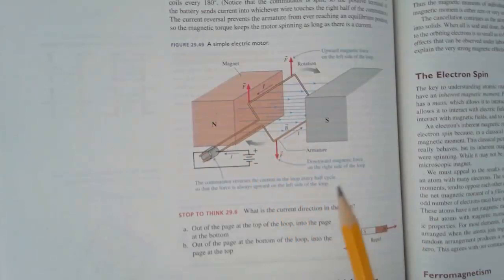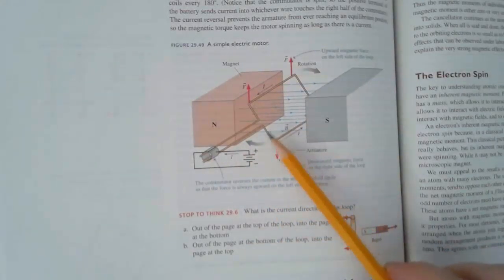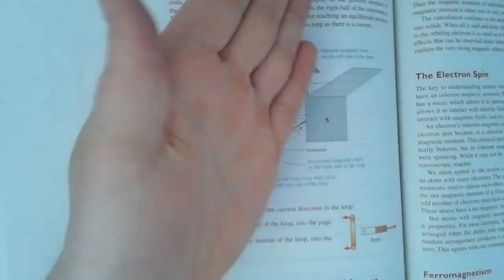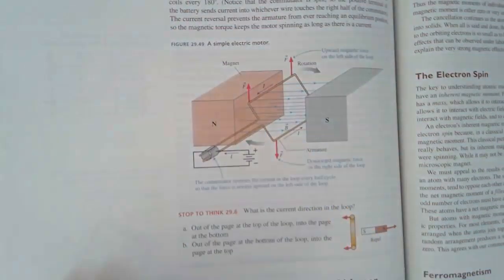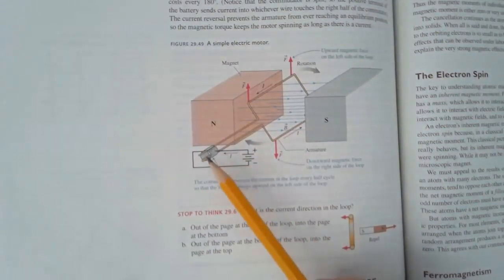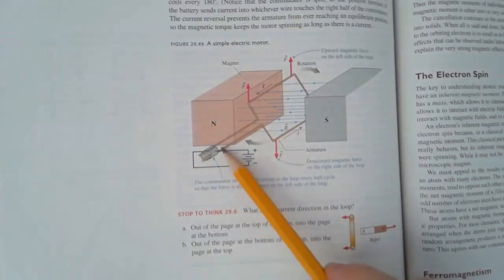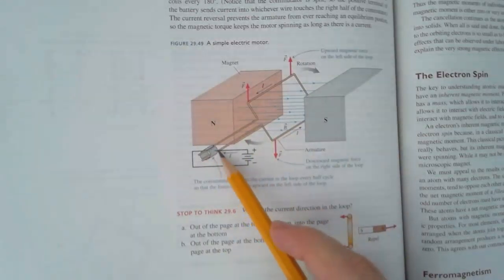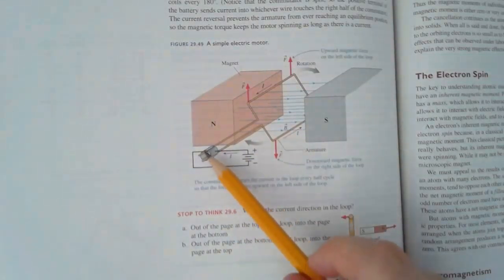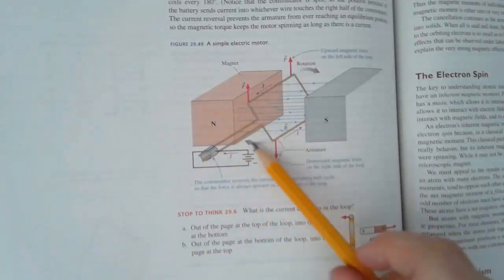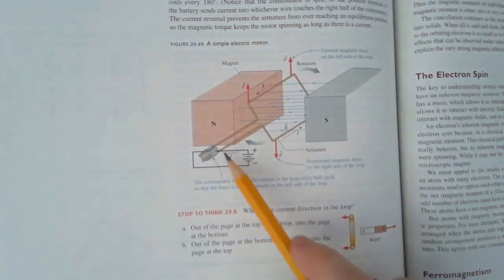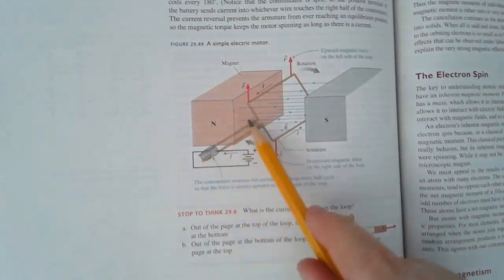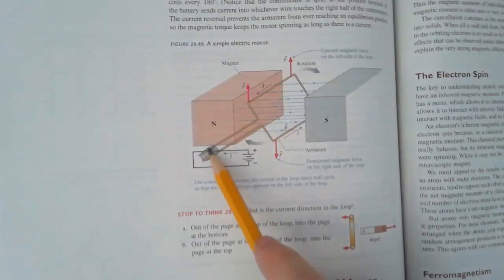But here comes the ingenious thought. Once it's spun to here, it wants to go here, and then you can figure out what it wants to do. But then you flip the way the two wires are connected. The way you do this is you have these wires here, and they brush against a thing called a commutator. As soon as this wire setup has turned enough, the direction that the current goes through this piece of wire flips because it's connected the other way around.